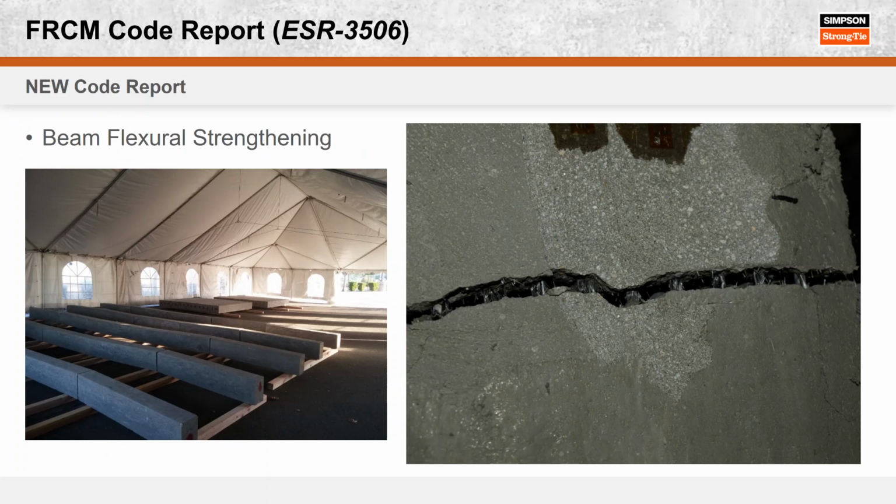So the image on the right shows, I think, one of our flexural beam specimens, and this is a picture looking at the bottom side where the grid basically slipped in the crack, and that was the failure of that particular beam. You see the grid pieces about every inch or so. But the grid did not rupture, correct? So the carbon is still intact. If we kept pushing, it would have ruptured eventually, or something would have given, but we just stopped because we weren't going to get any more load.